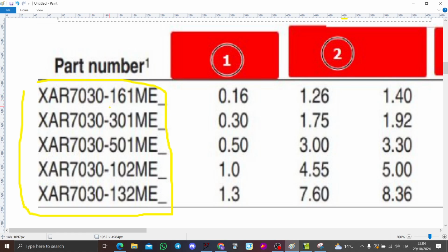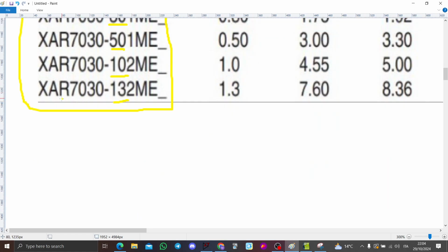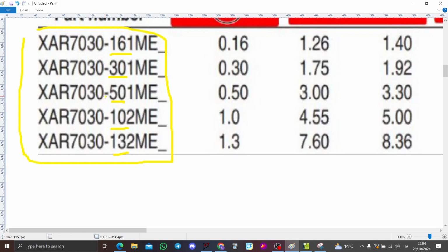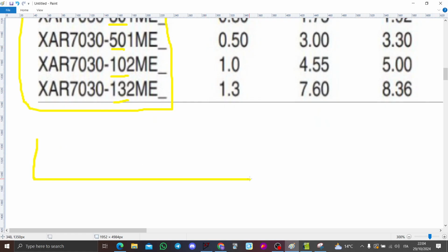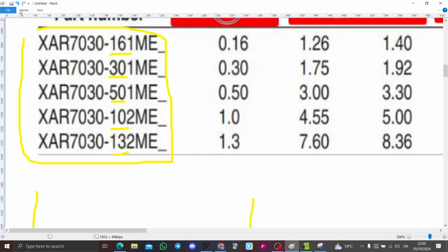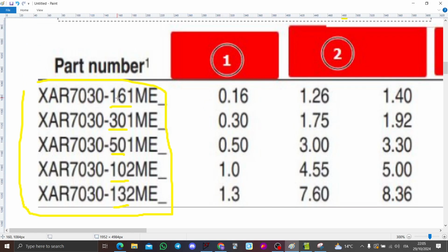Here there is 61, 31, 51, 102, 103. You have to know that engineers do compile the part number not randomly. Sometimes the part number contains information about the values. This happens with both capacitors and also inductors. So the main values are most of the time stored in the part number.